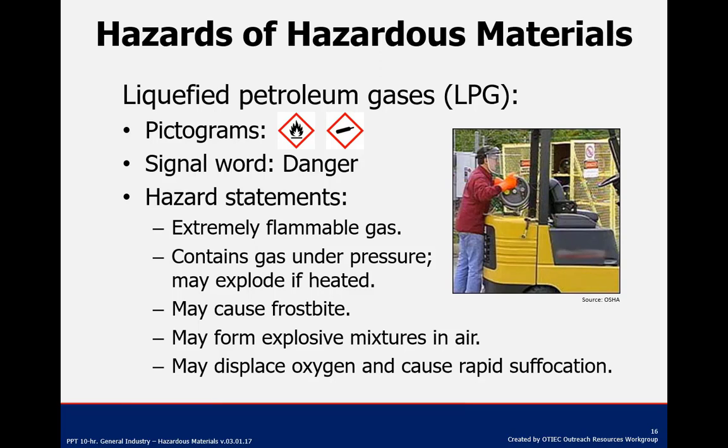LPGs, so liquid petroleum gas, you're going to see the flammable and the compressed gas pictogram. The signal word is obviously danger with these hazard statements: extremely flammable gas, contains gas under pressure, may cause frostbite, may form explosive mixtures in air, may displace oxygen and cause rapid suffocation. So you're going to see those associated with compressed natural gas.